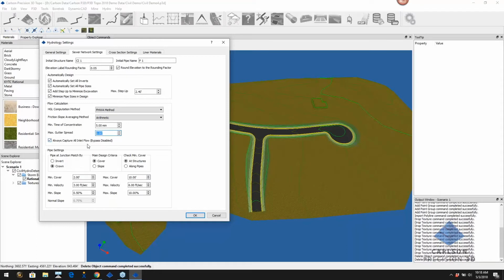That is assuming that every drop of rain that falls from the sky is going to go in that inlet. We know that don't happen, but again, we can assume it. So we're sizing pipes, basically saying every drop of rain is coming in the inlet. That's what this does. To me, this is another safety factor when you're sizing pipes.